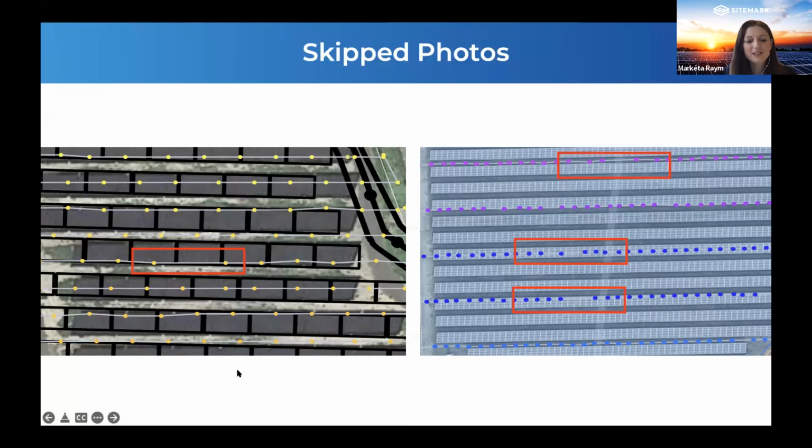And we know that every pilot is basically relying on the hardware, on the software, what application he's using, or what camera, what drone. All of this is a very important factor. And also, no matter how well you do the preparation in the flight program as a mapping flight, you set up the overlap, you set up the right GSD, and then you take off.